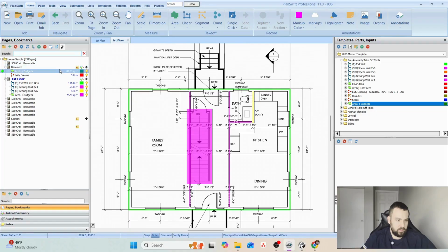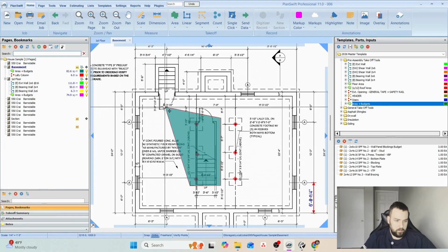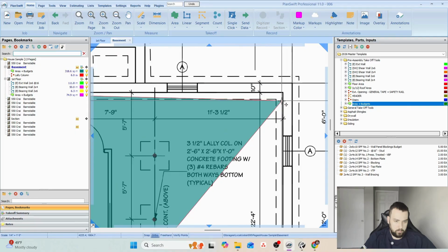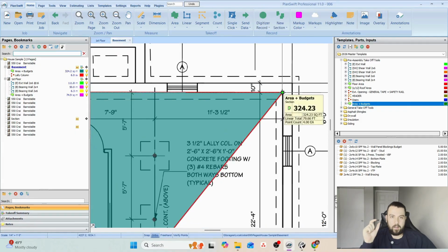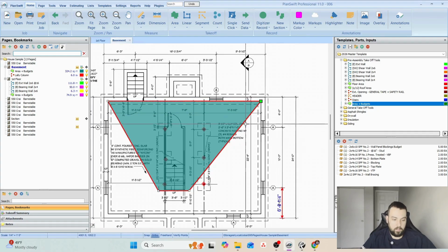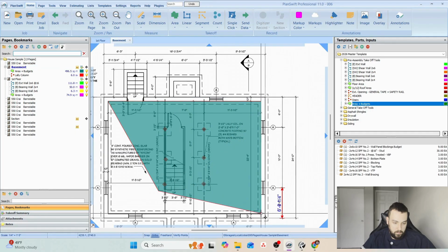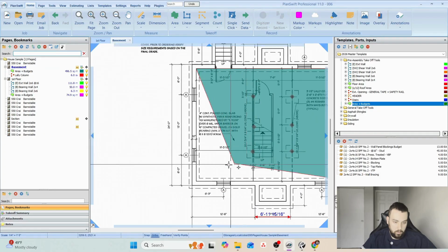Actually, I should play on the safe side. Let's just take the whole floor for budget, okay? I just thought, because this average of 90, 100, 105 linear footage at every 1,000 is considering areas without partition, you know, corridor areas. So let's just put everything, we'll just be covering, and the math respects that. Even so, we just have a stair here. I don't think it's gonna be a problem. I'm just playing the safe side. It's not gonna drive the price too high.